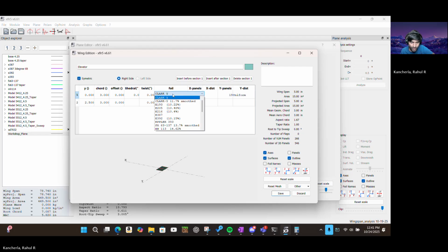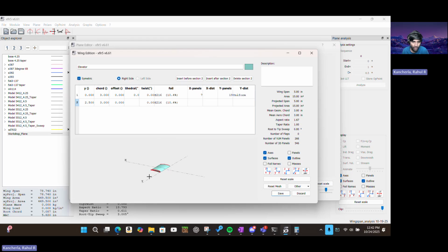And typically, you want a flatter airfoil for it. As you can see, 2414 was a little bit curved, and then E216 was really curved. So what you don't want your empennage to look like is something like this. I'll just find the top and the bottom. From what I know, you never want an empennage, at least for our purposes, to have a lot of, I'm pretty sure it's camber.